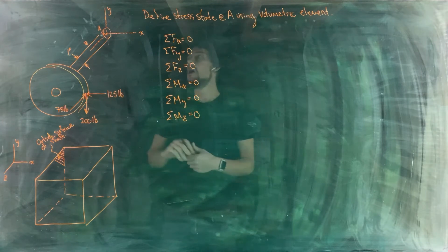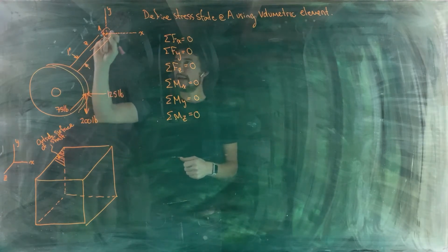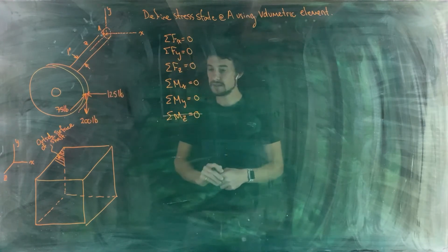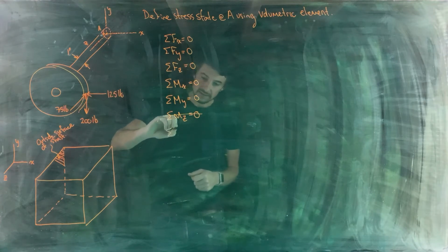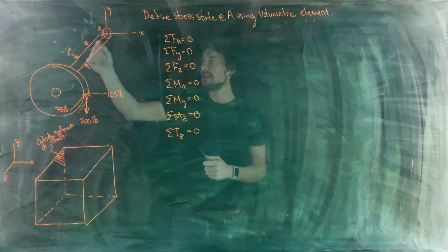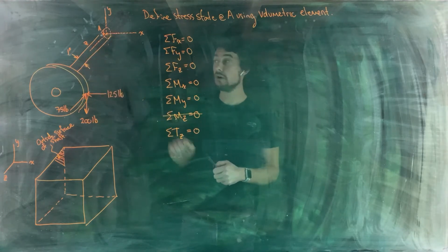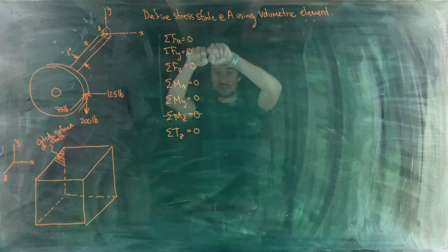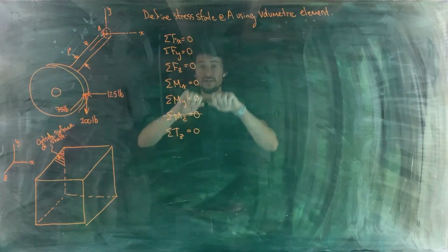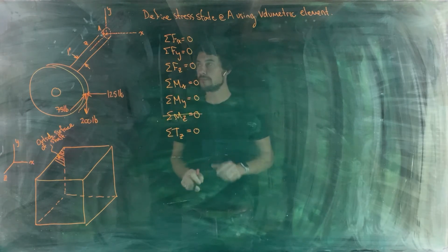All right, so in this case, the longitudinal axis of this shaft is the z-axis, so this should not be sum of the moments about the z-axis, it should be sum of the torques about the z-axis, since any internal things that occur around the z-axis are twisting the shaft, and that's a torque that's going to cause shear stress, not acting to bend, which is an internal moment.